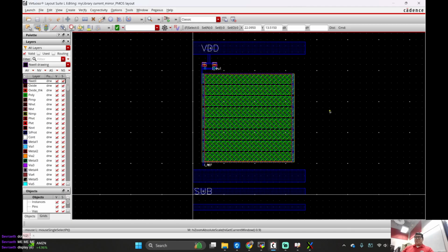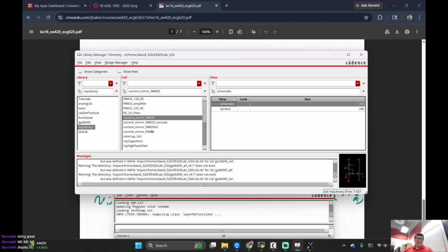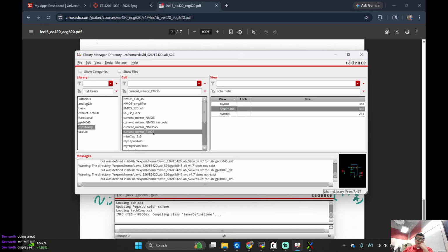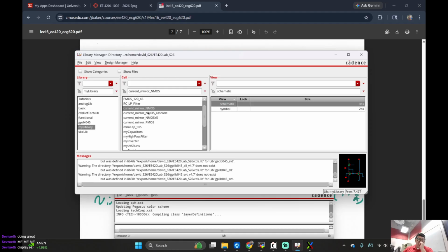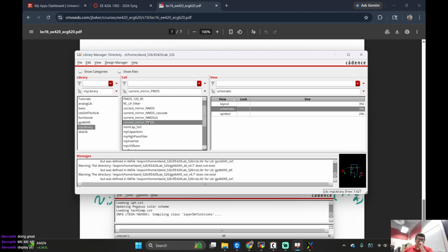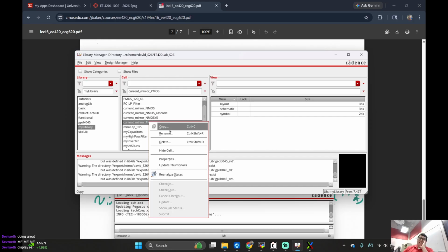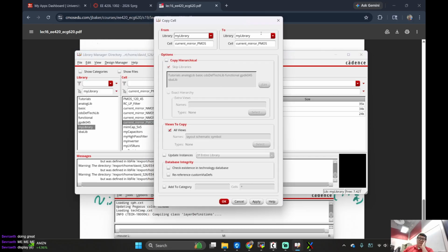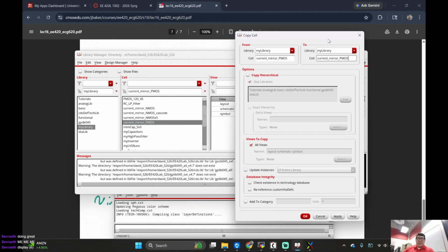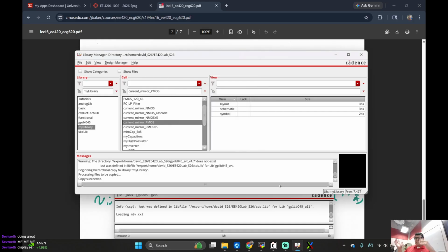But yeah, that's the PMOS, okay? So, you know what? I'm going to do something funnier. Let's get rid of that. What am I going to do for your PMOS times 5? See, NMOS, NMOS times 5, PMOS. Copy. Paste. Was it X5? Yeah, X5. Actually, copy hierarchical, just in case. You never know. Update instances. Okay. Let it do its thing.